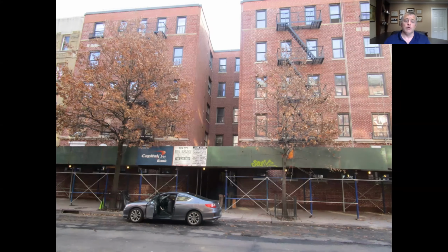And 2, those structures are typically fire rated, non-combustible construction, with fire sprinkler, fire alarm, and emergency lighting, much different life safety programs in place, so that you don't need to walk all the way down. Most of the time, they'll tell the residents, stay in your apartment, unless we're told, walk down the stairs and move out of the building in one of the multiple stairwells.